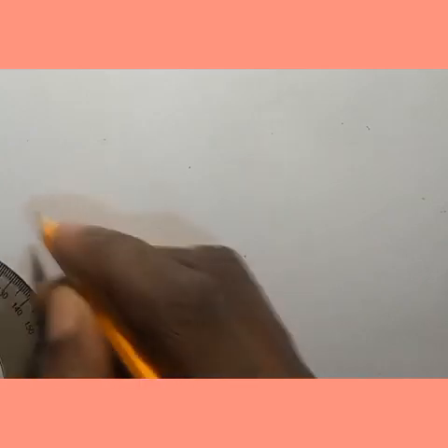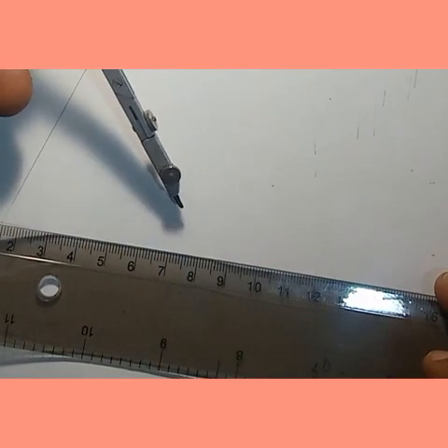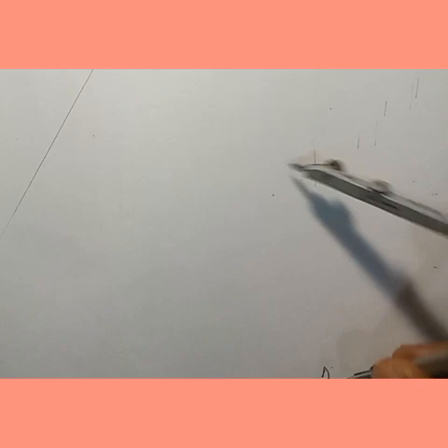So using this place as a reference, you place your protractor here, you measure an angle of 60 degrees here. So take your ruler and then you join. The length AB is given as 45 mm. Also link CD is given as 75 mm. So you take your compass, measure 75 mm. From point D, you draw an arc.